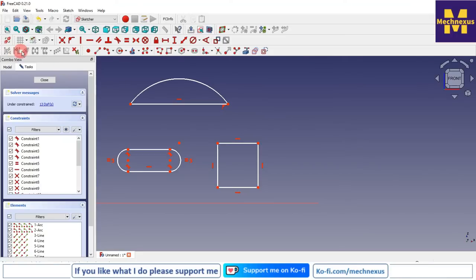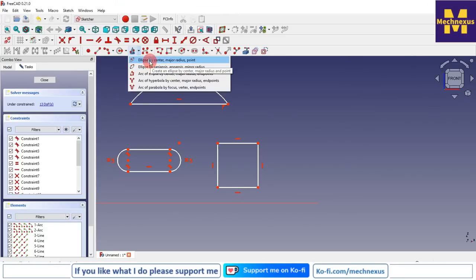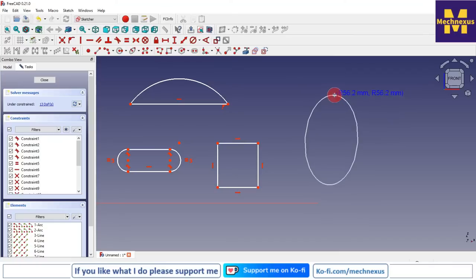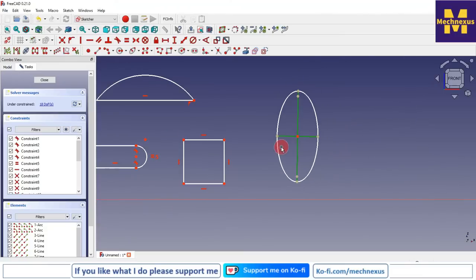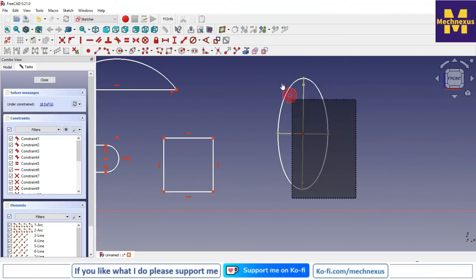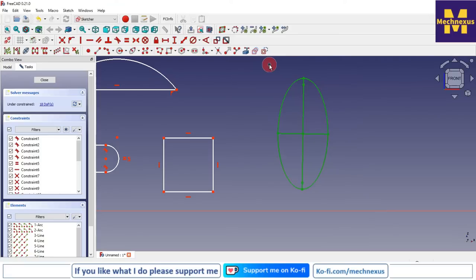The third tool we will understand is Show and Hide Internal Geometry. This tool is applicable when we draw an ellipse or parabola. So let's click on the ellipse by center, and I draw an ellipse. Now you can see that this is the internal geometry. If I want to show it, I can show it, or if I want to hide it, I will select my ellipse and click on hide geometry. You can see that the geometry we were previously seeing got hidden.